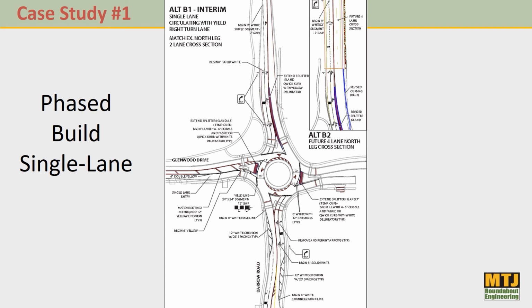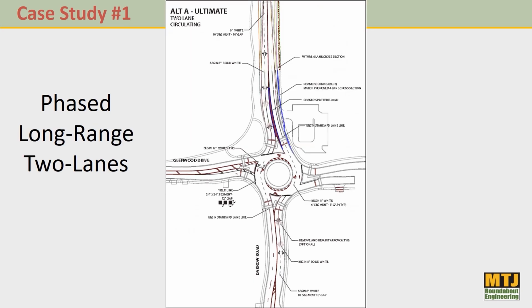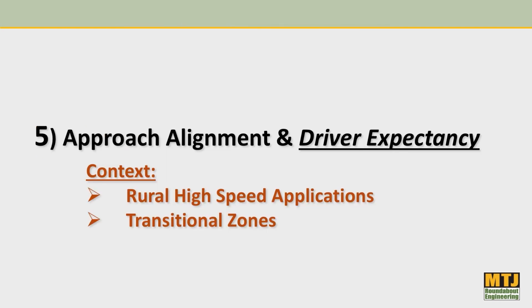In addition, the operational analysis showed that we didn't need all that laneage, so we could reduce the conflict points as well. So we opened it back up as a 2x1 roundabout, making that outside turn lane a right turn lane, with some curb line modifications. That will last most of the design year of this project based on the traffic projections. But we also have a phased plan where you can then bring that back to the two-lane roundabout when capacity is necessary.